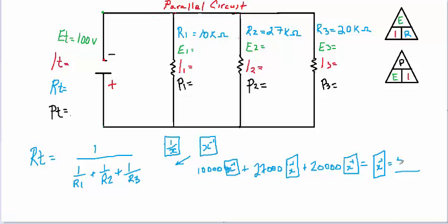The value you should have come to is 5,346 ohms. So that seems right, 5,346. We said it was going to be less than the smallest. So the smallest is 10K, so 5,346. And we're just going to put that into kilo ohm form. So we're just going to move 1, 2, 3 decimal places to the left. So I have 5.346 kilo ohms.